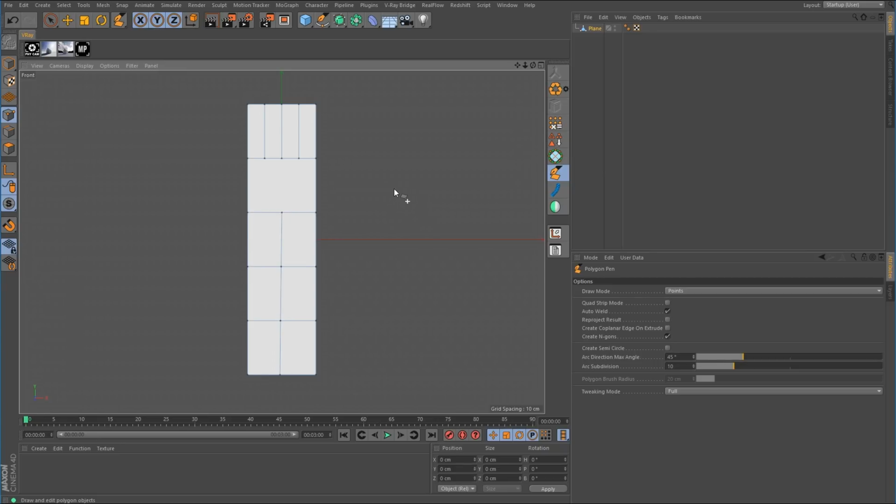All right, so the first thing that we want to do is this center line. We just need to keep it in line with the center line that we created coming from the bottom. So we'll just go ahead and connect those. And I'm going to make a horizontal cut across the center. I'm going to bring these 2 edges down to that, and then just weld those to the bottom. And there you go. So we went from 4 to 2. Actually, it's more like 4 to 1, 2, 3, 4, 5, 6 to 2. But we reduced it down somewhat, even though we got a couple extra quads in there. But that's one way of doing it, going from 4 to 2.